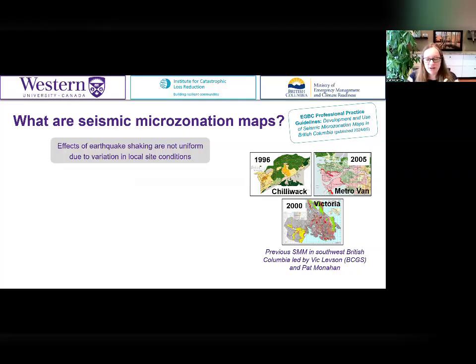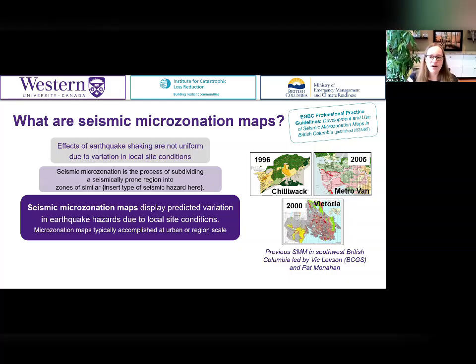It's the same earthquake, so the same magnitude. You're close to each other, so the distance apart shouldn't attenuate the seismic waves too much. But for some reason, I experienced it like a rapid vibration because I was on rock and you're on soft, thick soils and you felt like it was swaying and rocking. That's site effects. And we want to capture that or try to depict how that will vary for emergency planning purposes and other end use cases.